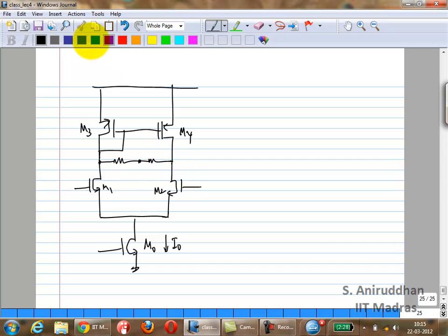And of course, remember that for free you actually get some parasitic capacitance here too, because we discussed that if you want to make large resistors you will get some parasitic capacitance. Plus you will also have the gate capacitance at that node.